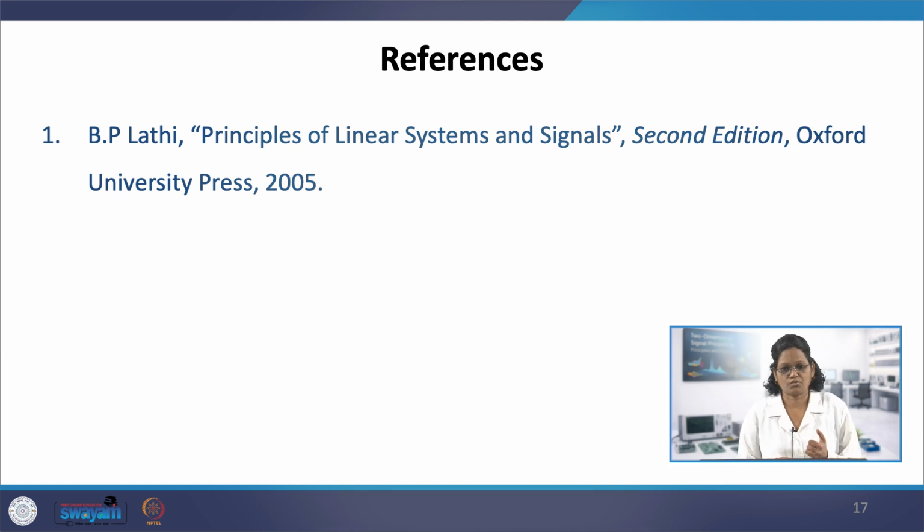Using this background of the z transform, that is the convergence, and that it is a generalized version of the Fourier transform, we can extend the 1D z transform to the 2D z transform. We will visualize the ROC, the region of convergence, which in 1D is defined in the z plane, where the axes are real of z and imaginary of z, with respect to a circle, or depends on the existence of the pole and the pole magnitude. That can be different in the case of the 2D z transform.